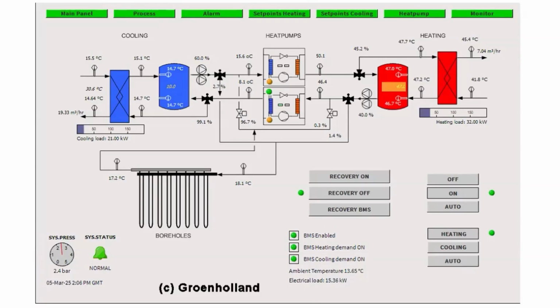so the buffer tank is used for decoupling of the flow rate over the plate heat exchanger and the heat pump, and at the same time it is used as a store if we have sufficient temperature difference, sufficient hysteresis on the set points. For instance, if we want to deliver 45 degrees to the building, we can have the buffer tank going between, let's say, 48 or 50 degrees and 45 degrees, still delivering 45 degrees to the building, but having storage in the tank as well.